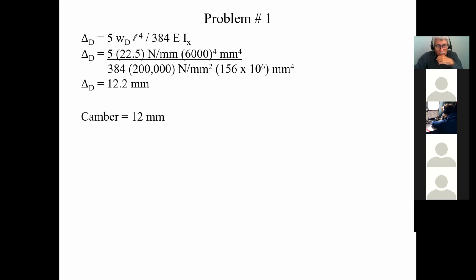As long as everything is below the MR and above the MF, there's no right or wrong answer. There's just a better choice. The only wrong answer is whatever you choose that causes a problem. In other words, if you choose a beam that's got a stiffness less than what you need, it can cause you a problem. If you choose an MF less than what you need, that can cause you a problem. If you choose an MR that is 3 times your MF, that will never cause you a problem. It's only going to cost you more money. Is that a problem? Not to you, to your client.